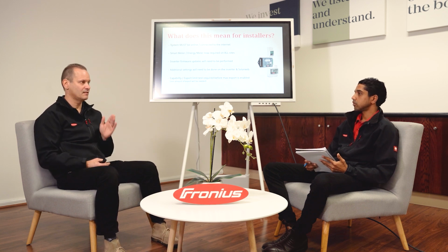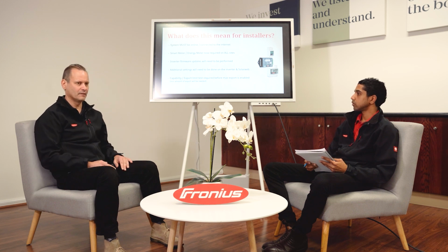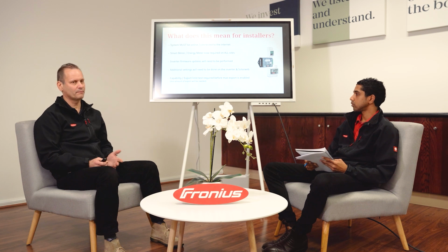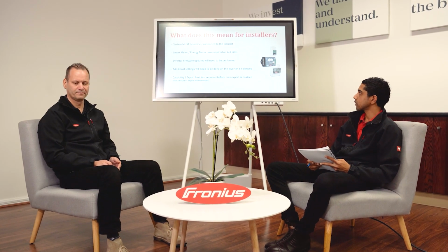So it's definitely not a tick and flick. From what I've heard, they're going to be quite strict with it. If it is not able to be connected to the internet, then they will be given a fixed limit of, depending on what the DNSP limit is, could be 500 watts, could be 1 kilowatt or 1.5. It's not 100% set in stone yet.